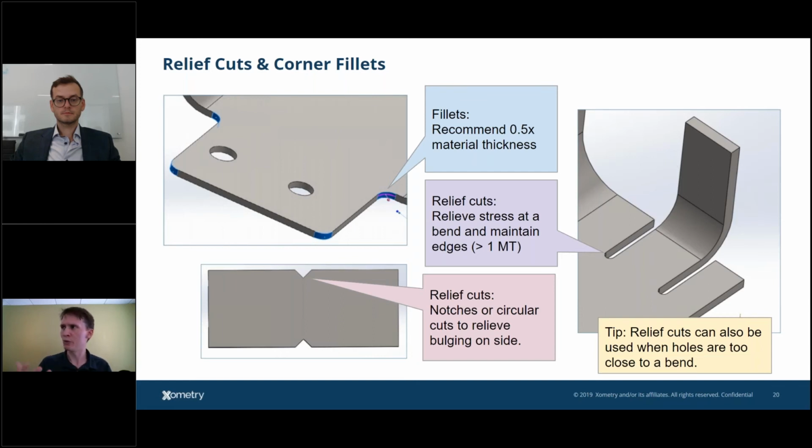And I think, Callye, we were talking about how sometimes you could even outline the hole with almost a 3-sided box, creating a relief cut right near a bend, and the hole just turns into a diving board next to your bend. Yep. That's extra helpful if you need to put in PEM hardware, which we're going to talk about in a second, because there you have a lot of center of hole to edge constraints on that hardware.